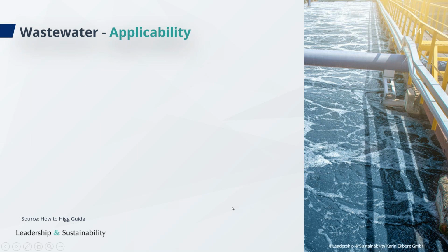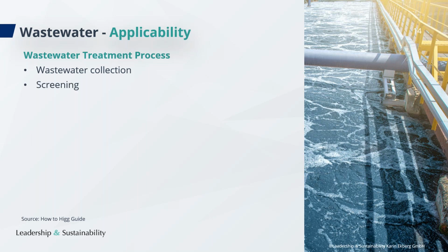And when we walk through all these different steps, we have the wastewater collection, and the wastewater is collected via drainage pipes and directed to a central point. The pipes or tracks should be leak-proof, and the people offering exhaust services should, of course, use PPE, personal protective equipment, as well. Then the screening process. This process involves the removal of large objects that could damage the equipment.